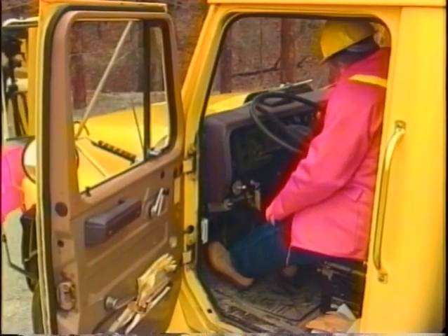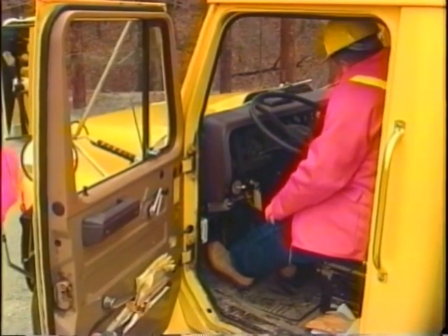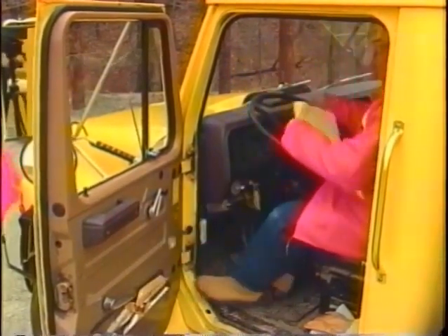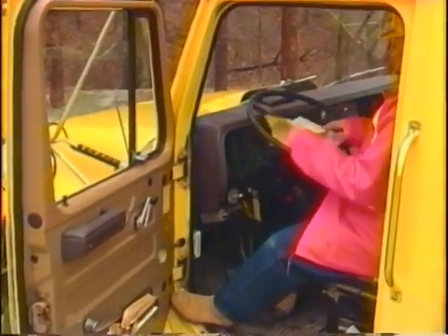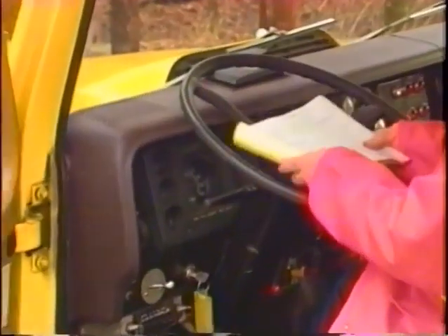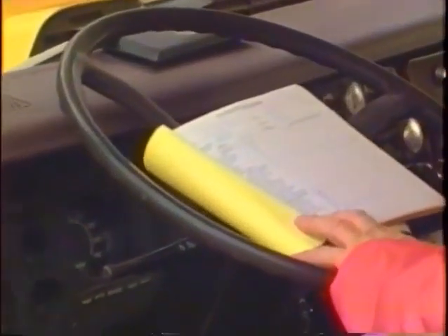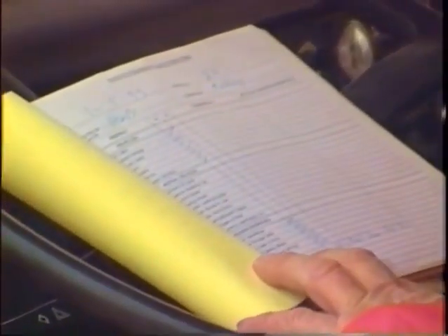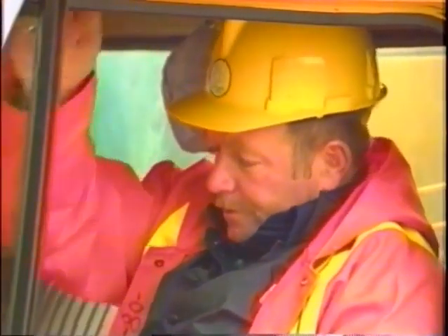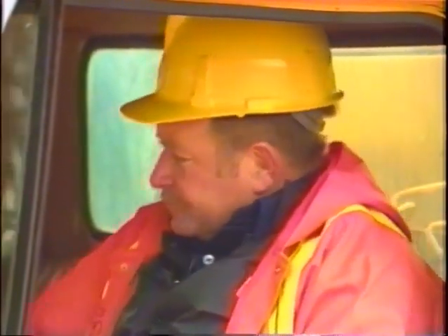It may seem surprising, but in the first part of your hydraulic check, you don't look at the vehicle. Instead, examine the vehicle's logbooks. Are the filters, strainers, or magnetic plug due for servicing? Does the oil need to be changed? If so, arrange to have the work done by a qualified mechanic.